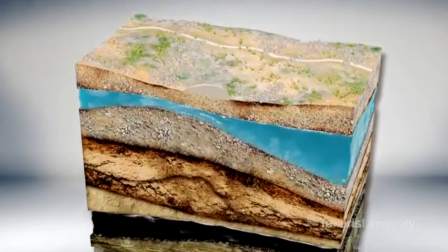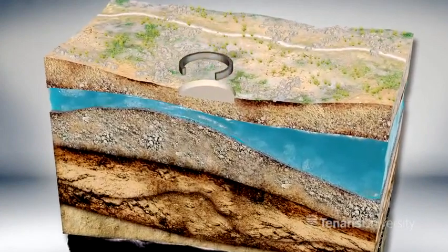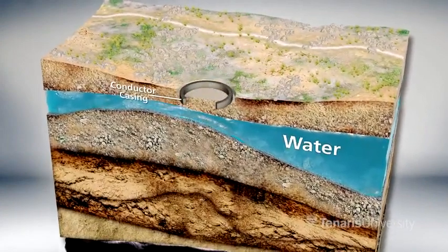We will start drilling our well, and the first casing to be run is the conductor. This is required to circulate the drilling fluid up to the surface without eroding the upper sediments below the rig foundations.